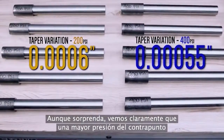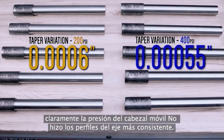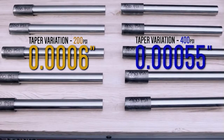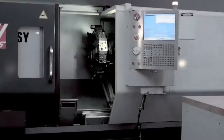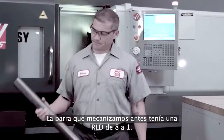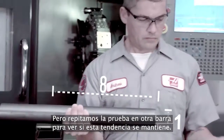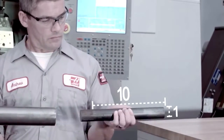Maybe this seems surprising, but we can clearly see that more tailstock pressure did not make the shaft profiles any more consistent. The large shaft that we just cut had a supported L to D of 8:1. But let's repeat this test on a different shaft to see if this trend holds up.